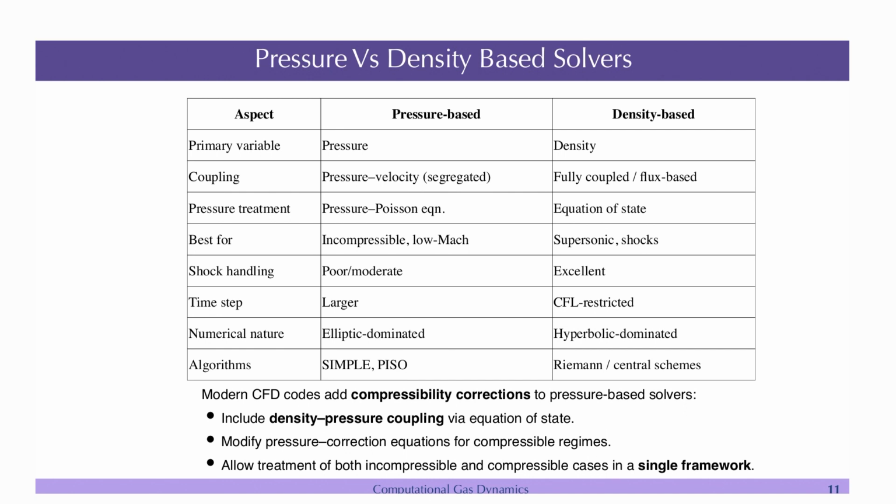So, if you look at Fluent or any solver, there will be pressure based and density based solvers. For example, most of the solvers in OpenFOAM are pressure based, but there are one or two density based. For example, rhoCentralFoam is a density based solver.